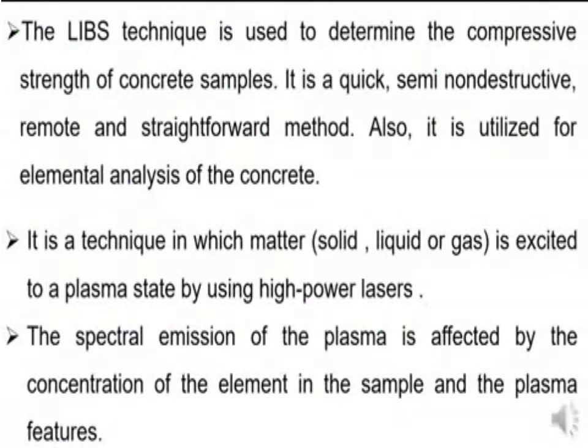We will measure the compressive strength of concrete by using the LIBS technique. The main advantage of the LIBS technique is that it is a quick, semi-non-destructive, remote, and straightforward method. Besides, it can be used to measure the elementary analysis of the concrete. It is a technique in which matter, solid, liquid, or gas, is excited to a plasma state by using high power lasers. The spectral emission of the plasma is affected by the concentration of the element in the sample and the plasma features.